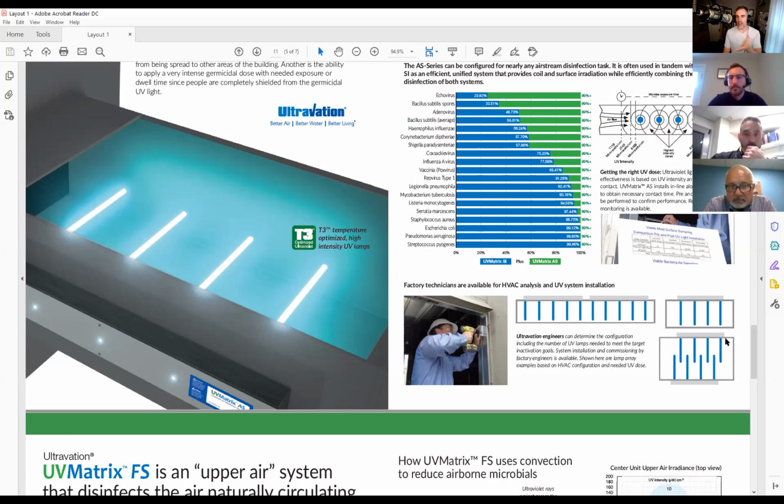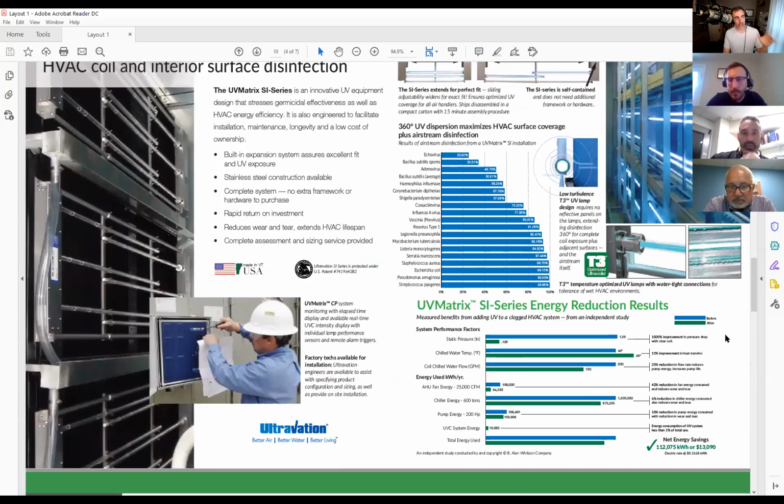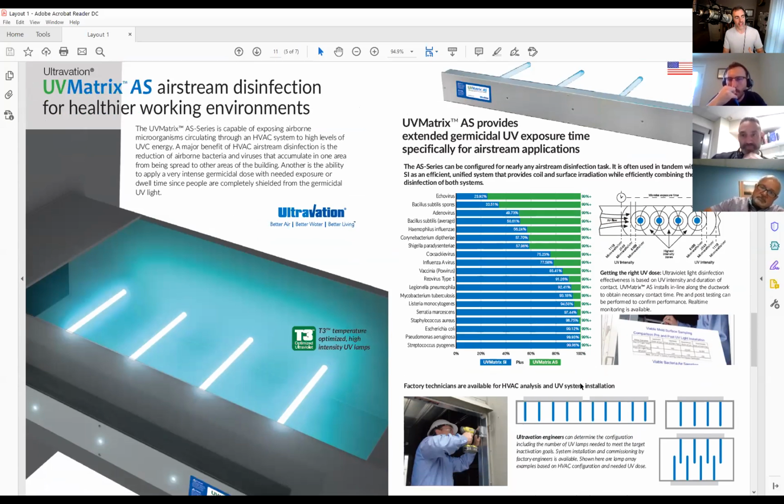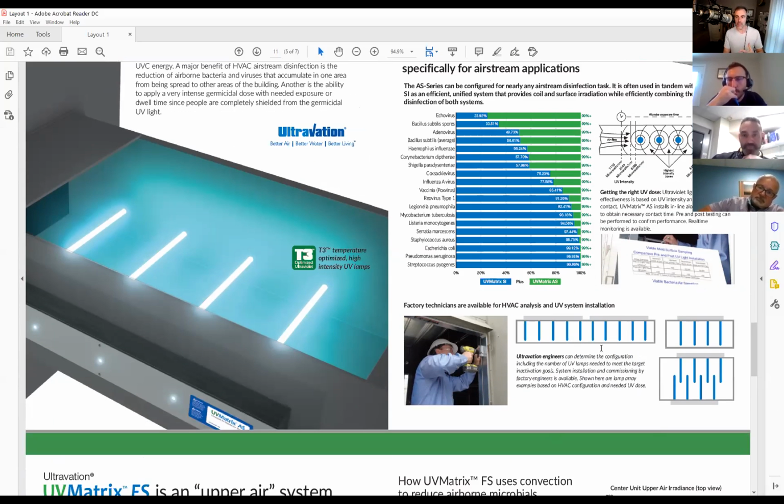That's why eventually when you get your quote back, you'll have those examples. That's why it's so important. Okay, how big is the equipment? How big are the coils, at least for up here? And then, okay, now how much air is being pushed through? How big are the supply ducts? How fast is the air moving? And then what is your goal of disinfection rate? Because then that'll determine how we can apply the AS model into the design. Exactly. Yeah, I sent you some sizing of pretty big coils of pretty much our biggest area. So probably almost about 25,000 CFMs coming out of.